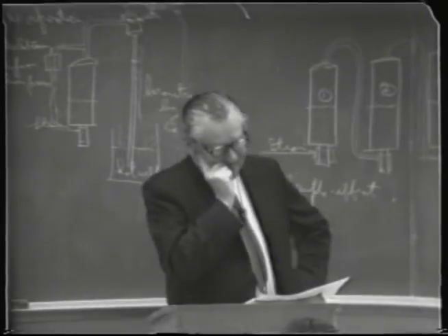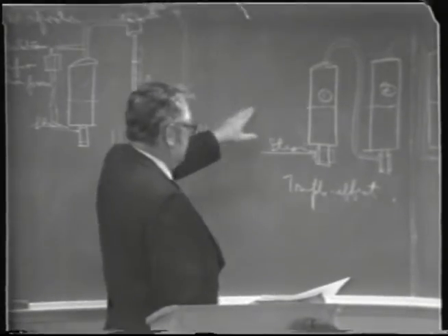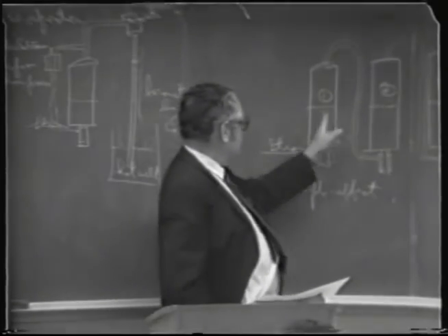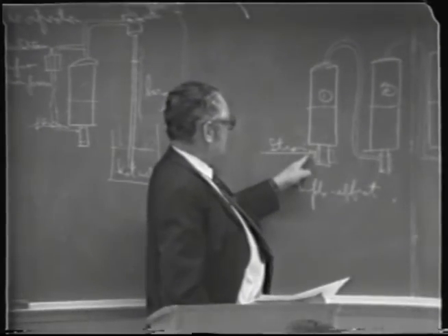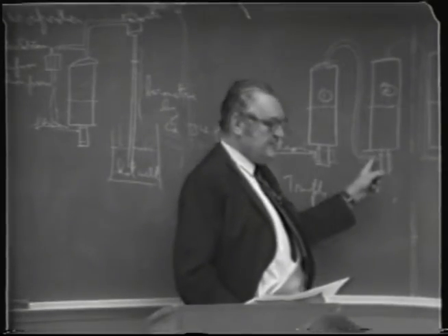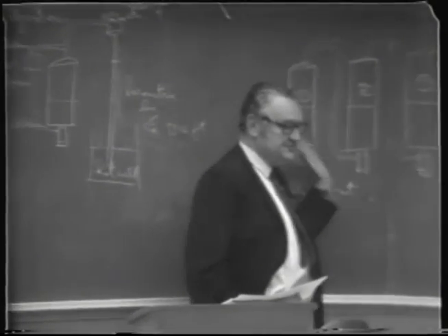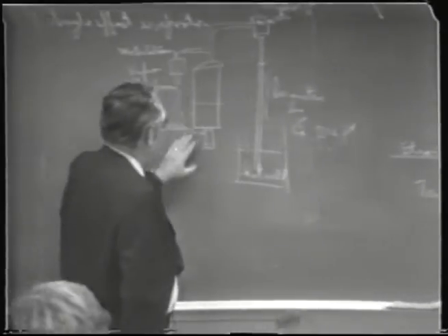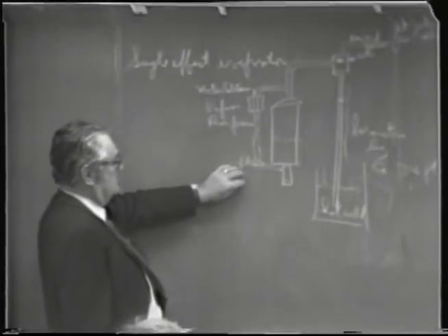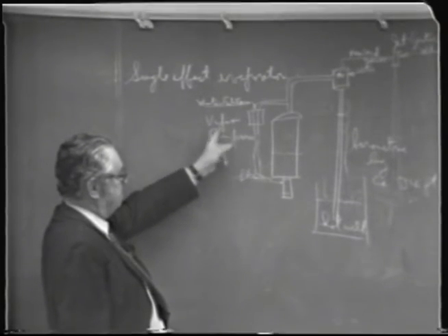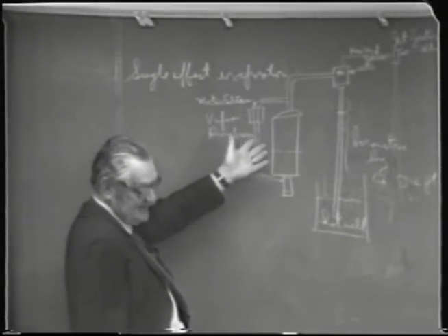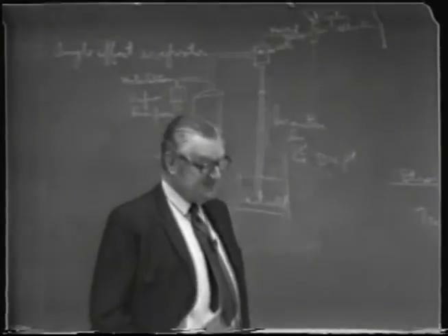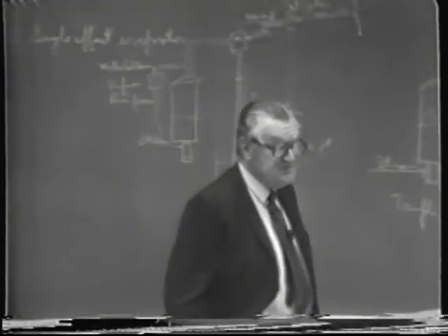So anyway, theoretically, you could put a vapor compressor on this here. But since you're going to reuse the vapor anyway, there isn't too much advantage in doing it in a multiple effect. But there's considerable advantage in doing it in a single effect, because as this indicates here, you may be able to get as much as two-thirds, three-quarters of the steam saved.